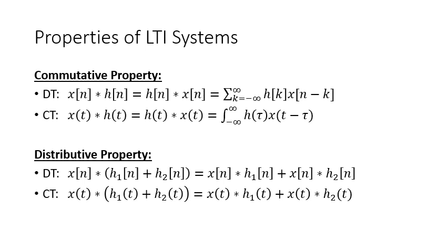So we add it so that the resulting discrete time signal shifts to the leftmost, and then you multiply the corresponding values, then you sum them, and then you shift the signal, right? Like we use the word SMS. That means shift, multiply, and sum. This is for the discrete time case, okay? And you keep doing this. For the continuous time case, we do the same thing, but instead of summation, we do the integration, right?